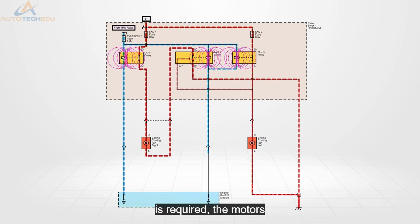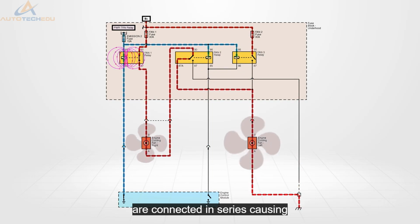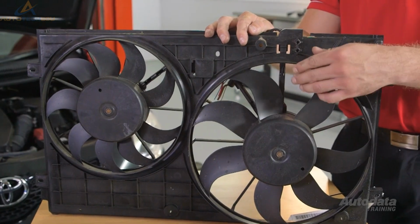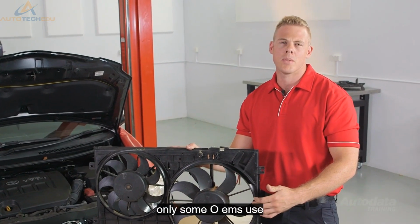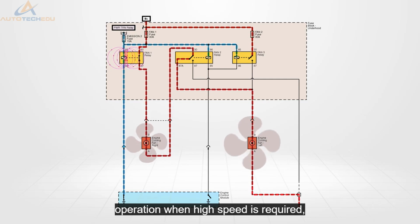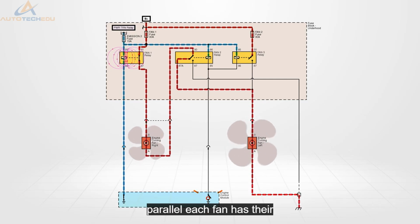When the low speed fan is required, the motors are connected in series, causing a voltage drop which reduces both motors' RPM. Only some OEMs use this type of mid-speed operation. When high speed is required, the fans will operate in parallel.